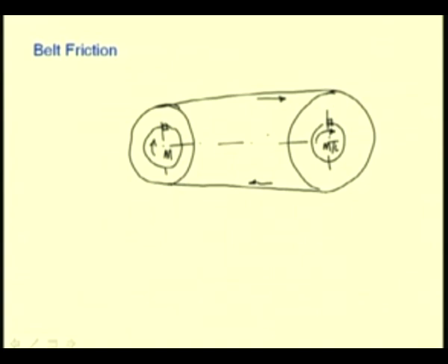Also, the center distances can be varied, that means we can place the motor in a location where we have suitability for connections and we can place the machinery in its suitable position. So, these are some of the advantages why we employ these belt drives. Particularly, you would have seen this in rice mills or in other industrial machinery also.